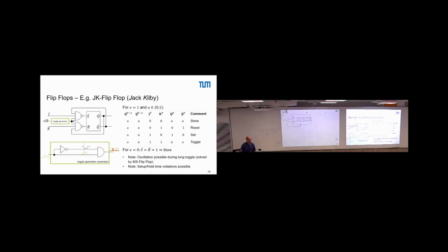What happens now? We have two parts here. First latch, second latch. The first latch here can also be seen as level triggered flip-flop. So as long as our clock is, are there any questions? So as long as the clock here is at 1, the output here is controlled by J, K, and the internal state. Yeah? Internal state inside of the state that we see here.